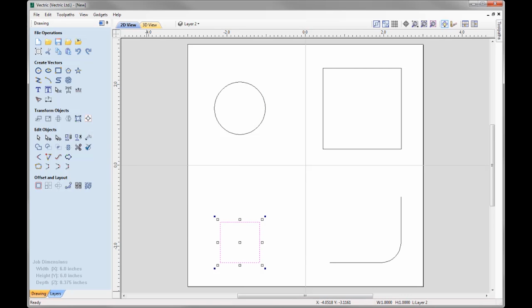without using the alignment tools. So not only can we make use of the Smart Snapping when drawing shapes and aligning shapes, but we can also make use of the Smart Snapping when we're in Node Edit mode. For example, with this square selected, let's press N on the keyboard. I'm just going to press C to cut this point here, then I'm going to take that node, and you'll see that I'm able to follow along that vertical extension there. I'm able to snap to various points with other objects that we may have in our job. So it just makes life a lot easier being able to snap to all of the various points from various objects when in node edit mode. And so the addition of smart snapping makes drawing and aligning vectors so much easier to do than in previous versions.